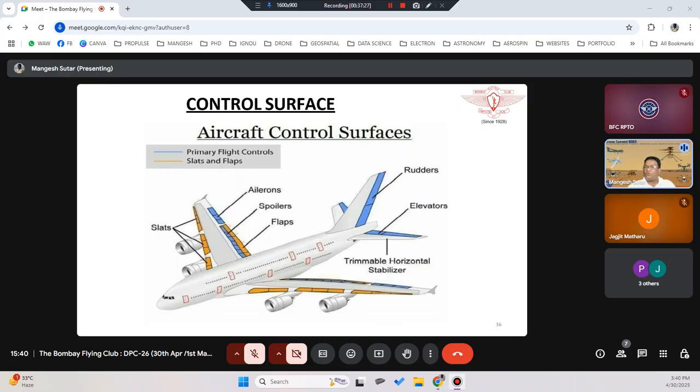When you are flying the drone, these are the important concepts you need to know. When you are using the joysticks, you should know which joystick controls what. You have two joysticks in your hand, and each joystick will control two channels. One joystick will be responsible for pitch and yaw, and the other for throttle and roll motions. We'll see which joystick controls what in the subsequent slides.